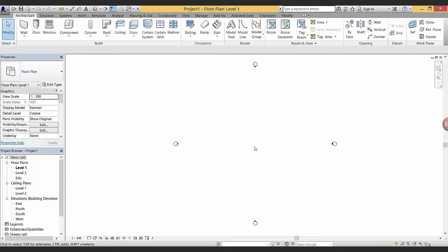So we'll be designing a building that I worked on at Dark Architects, my current employer, and we're going to start by using the Revit origin as a basis for a grid. So the origin, when you're in level 1 in the project browser, I'll come back to explaining what's with the menus on top, the property palette, and the project browser as we go.